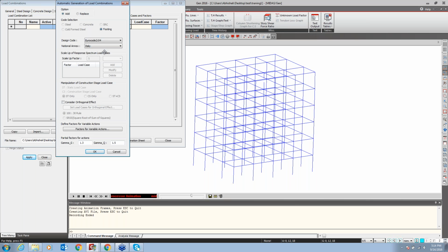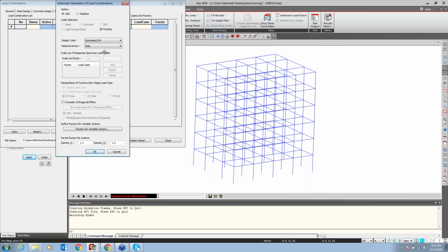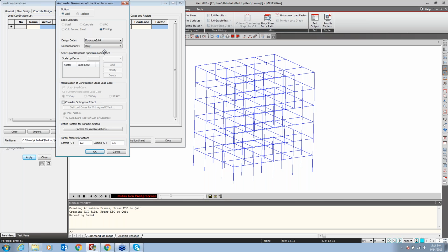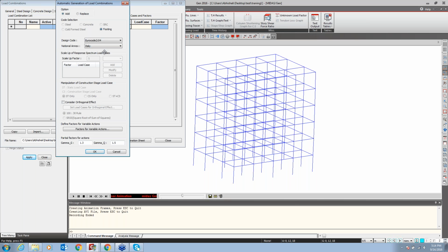Based on that, it will give you the area as well as the steel in the design plus, and here you can check for sizing purposes, but that is based on the BS and ACI code in Midas Gen. But if you use the design plus, then it is basically as per IS 456.